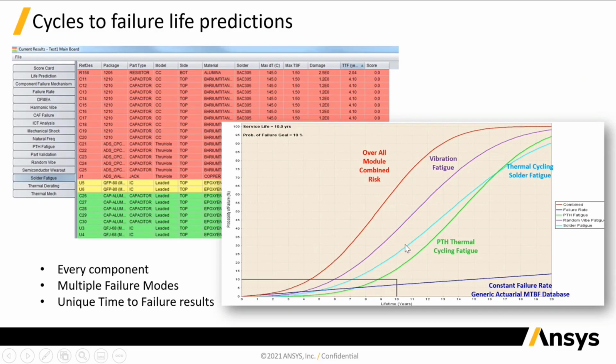Just to reference that to MTBF calculations, the MTBF calculations from things like the Mil Standard Handbook are based on a series of tabular results for individual components that are then linearized across a time period. And that doesn't really take into account the nonlinear materials, the changes in those materials based on the changes in the environment.